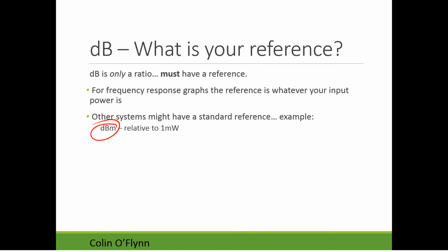The reason we use dBs is that if we have a huge variation of power, it's a really convenient and easy way to represent it. And later we'll have some niceties when we're combining amplifier stages, in how we analyze that by just adding decibels.